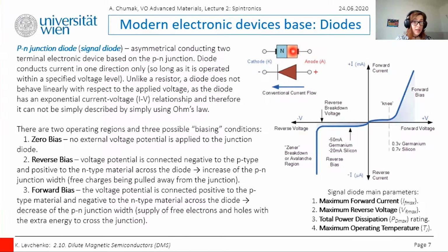However, as you may see, when we increase voltage up to the point of the reverse breakdown voltage, we may cause an overheat due to the avalanche effect. Consequently, the diode becomes shorted and maximum circuit current starts flowing, which is indicated by the step downward in the plot.